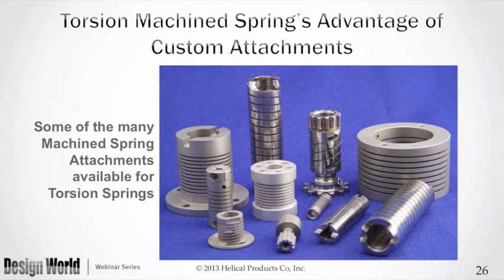But we also know that in all gear systems, even these wonderful jet engines we have, there's a little bit of harmonic because nothing is as perfect as can be, and so there's a little bit of torsional hunting in the system, and that was prematurely breaking that fuse. And what's done is a triple start flexure was put in that torsional spring to take out that increase and decrease and increase and decrease in torque going across the shear section. So that's been a very successful design.